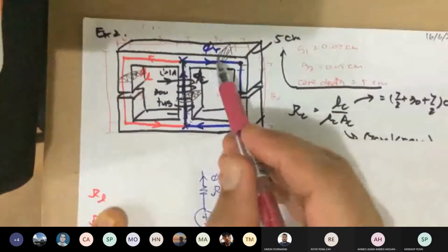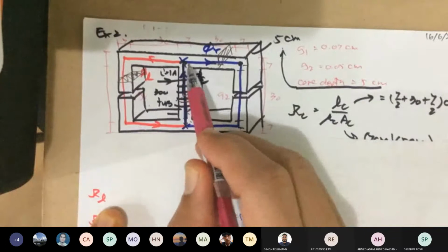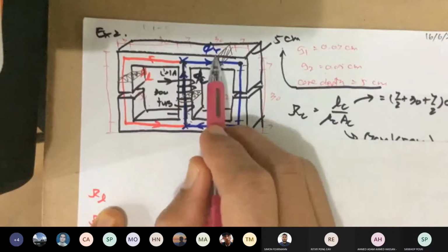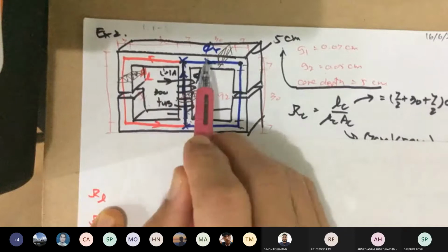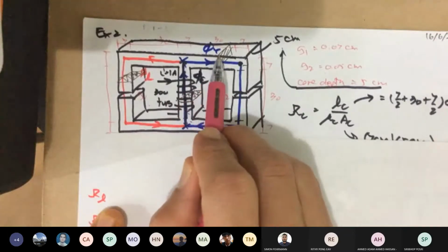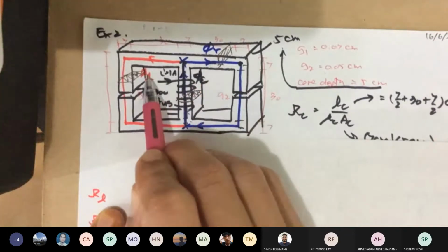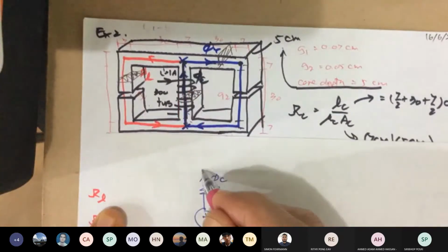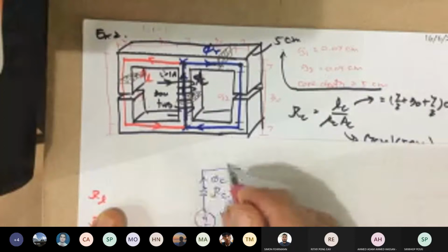And then when you come to this point, the flux branches out towards the right and the left. The blue and the red. Shown here is phi R for the right, phi L for the left. Again, it's passing through the core, so you go up, go to the right, phi R, go to the left, phi L. Now the individual path of the flux flows through different materials.